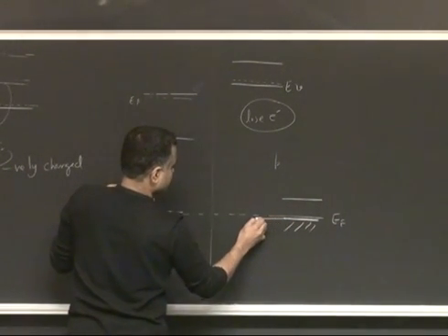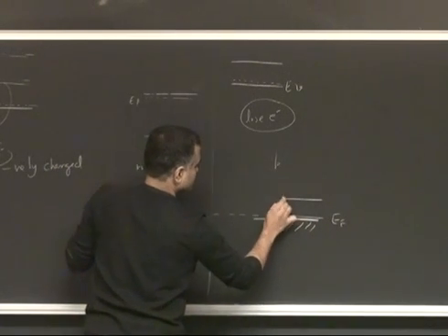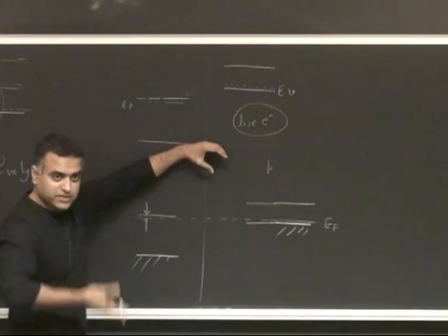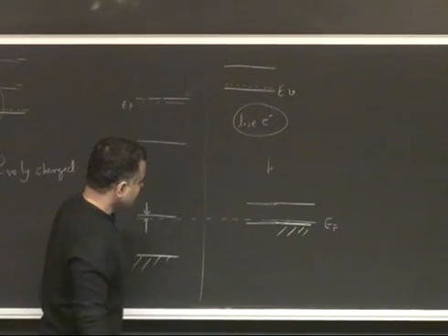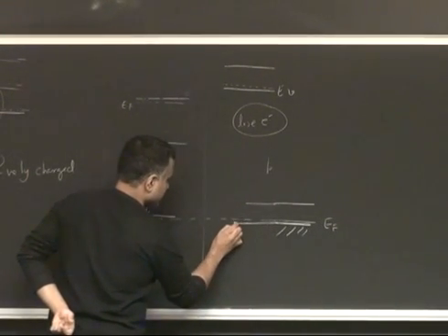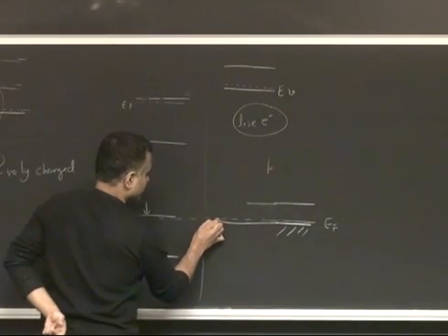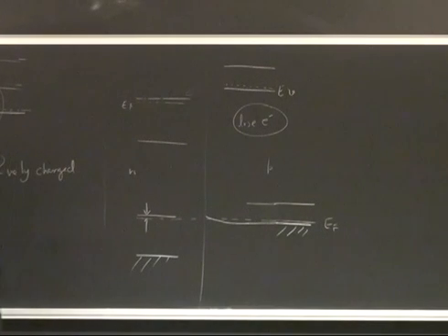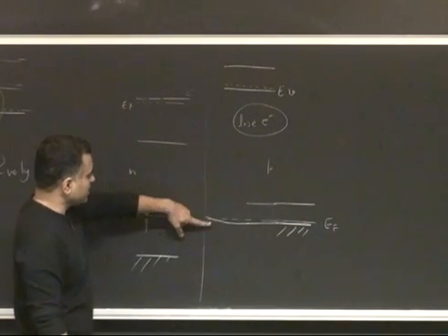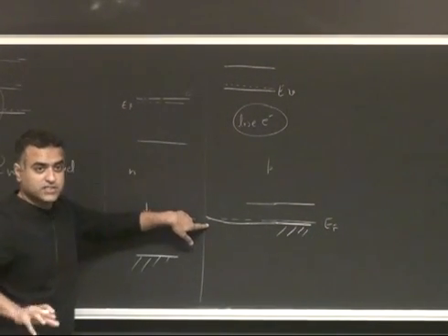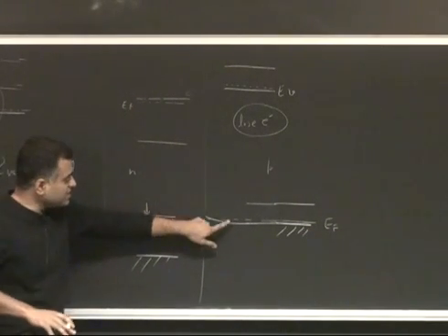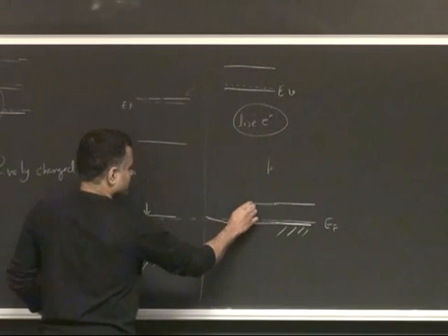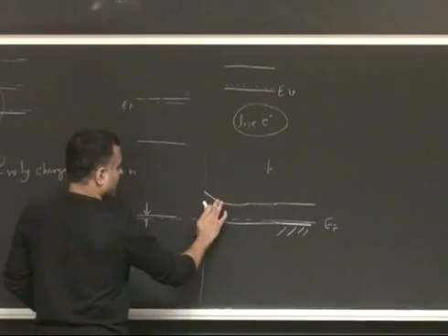So what you will end up getting here is, whenever you lose electrons, you gain positive charge. And whenever that happens, the band is going to bend up. So whenever there's positive charge, the bands bend up. But I think you also realize that the bands will start bending, but they cannot bend too much, because once the Fermi level enters the valence band, the DOS is very high. The density of states is very high now, right? So it's going to bend up initially sharply, but then it gets kind of stuck because of very large DOS.